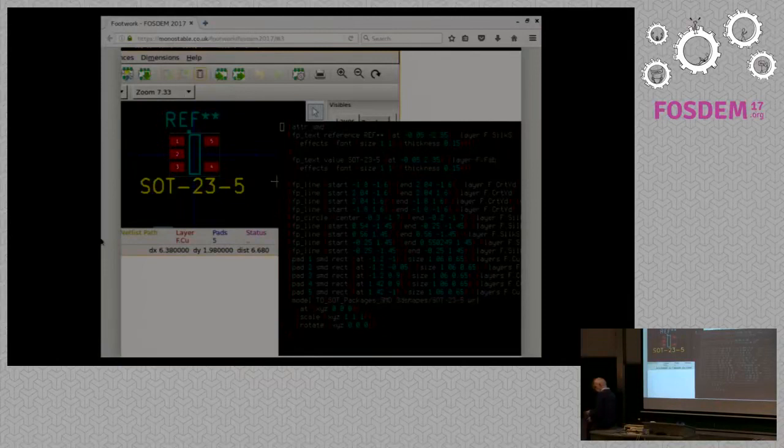Like in FreeCAD, for instance, if you have a flange and you have put in 10 holes, and you augment the diameter of the flange, it will either disperse the 10 holes over the wider diameter, or, if you fix the diameter, it puts in 2 more holes. So that's parametric. That's about the gist of it.